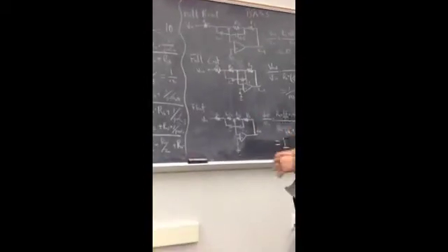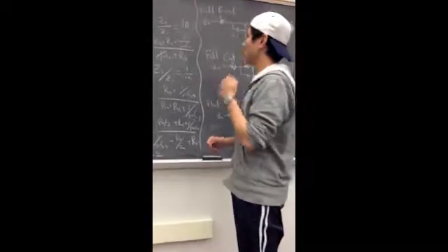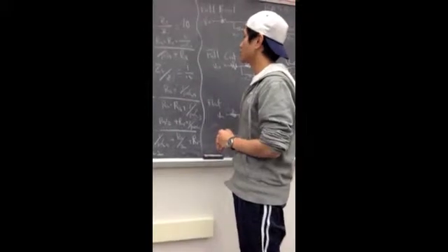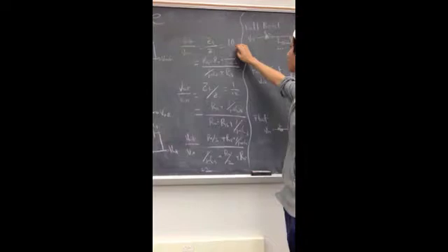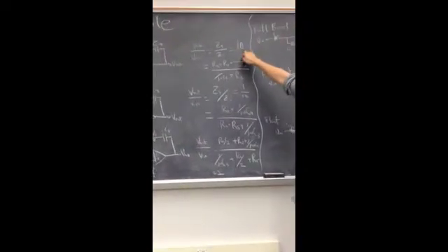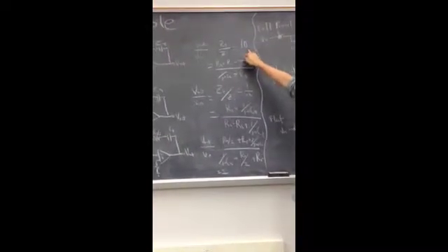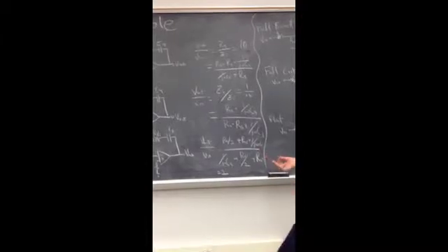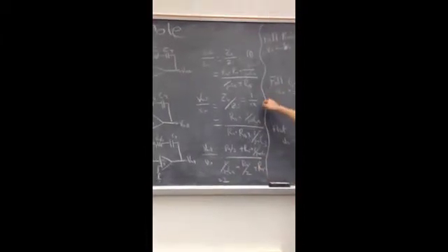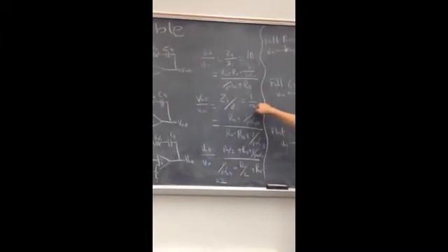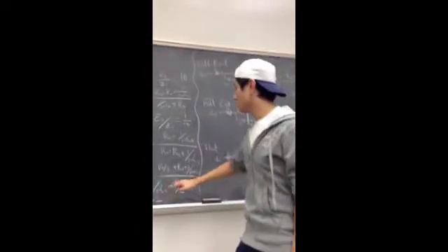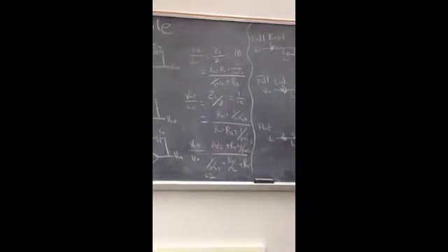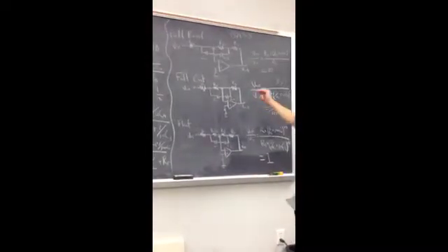What we're expecting is that for the highest frequencies, we would be able to get a gain of 10 times, which is a decibel gain of 20 dB for a full boost scenario, and a cut of 1/10, which is a decibel loss of -20 dB for a full cut scenario, and no boost or cut for a flat scenario, and similarly for the bass, the low frequencies.